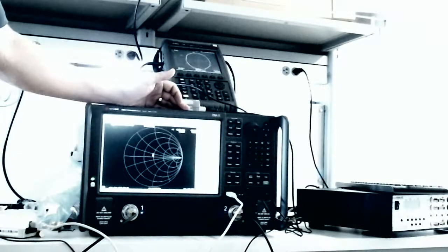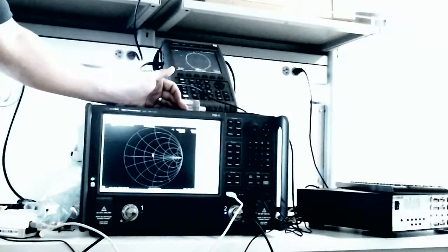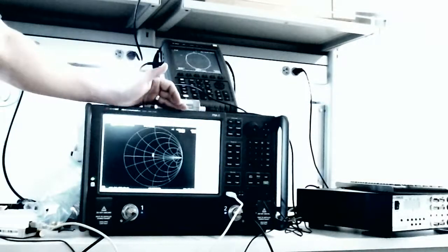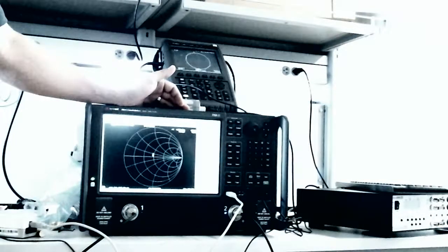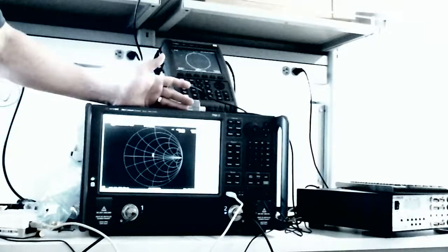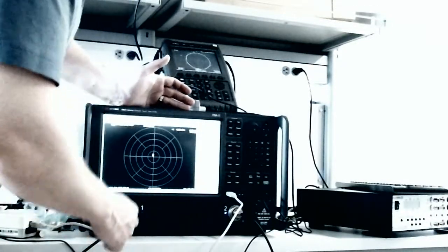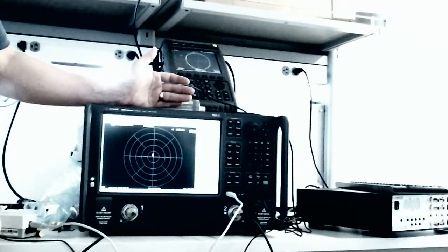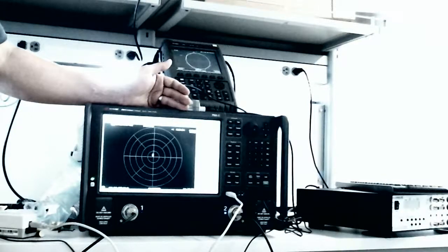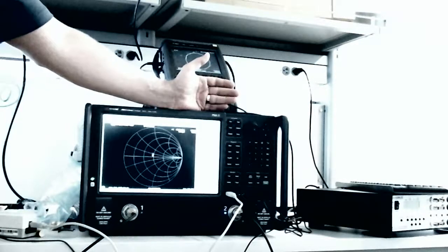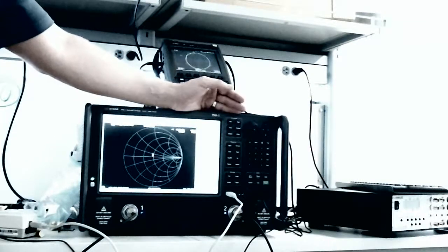Or it will give S parameters in it. So it depends on what format you are, right? Because this will give us the S real and imaginary, I think. Yes. But depending on what format you're plotting it in, right? So if you wanted to, you could plot it in polar, and that could give you S in real and imaginary. Or you could look at it on the Smith chart. I mean directly converting S to Z. Yes. So when you do Smith, that's what it does. With the S11, it takes it and plots it on the Smith chart, which is effectively R plus JX, right?